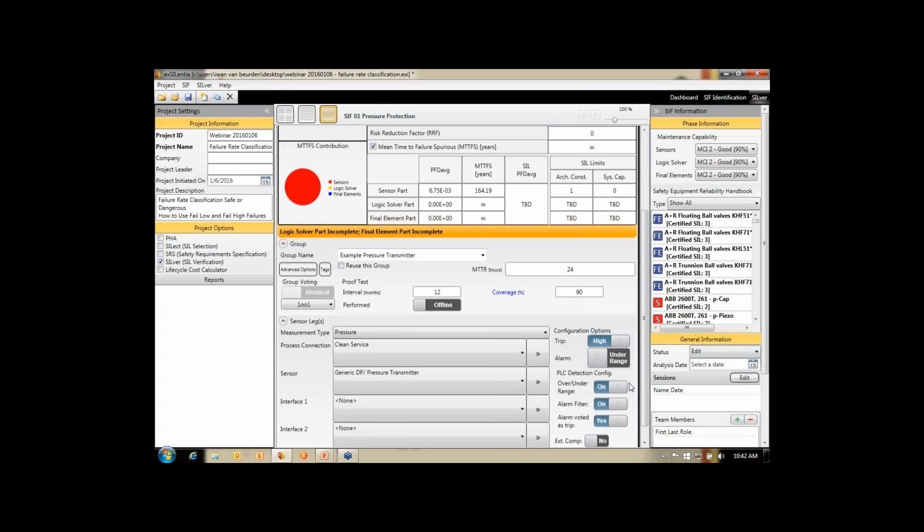So the fail detected failure mode will have a higher failure rate than this example. And you will see at that point that not detecting those failures, which are detected internal to the transmitter, on the application level will significantly impact your overall probability of failure on demand. You're basically losing all the diagnostics that the manufacturer built in.